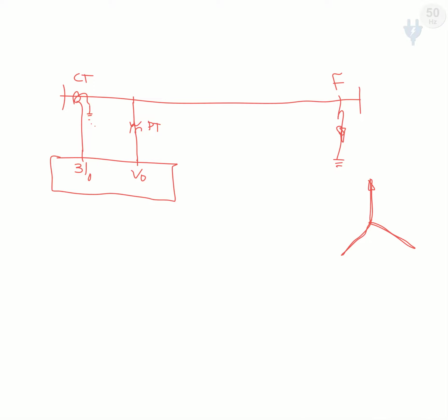We know the positive sequence voltage phasors VA1, VB1 and VC1 in the normal condition. During the fault, for example, VA1 becomes around 0 in the type of resistive fault. The V0, meaning the zero sequence voltage, becomes